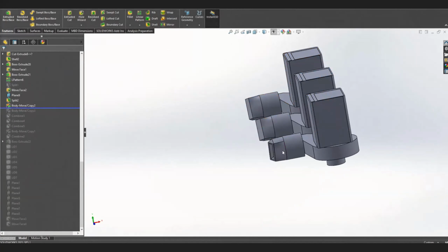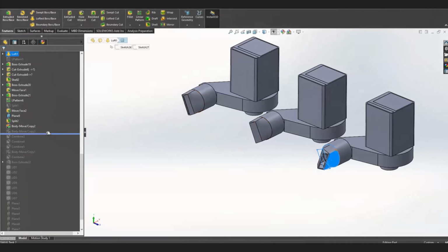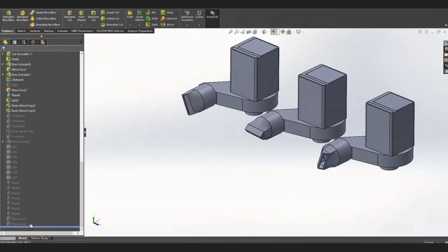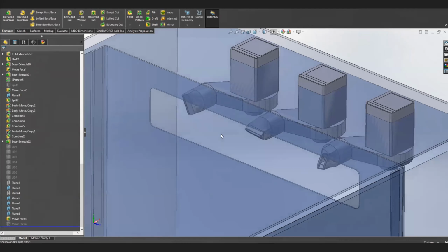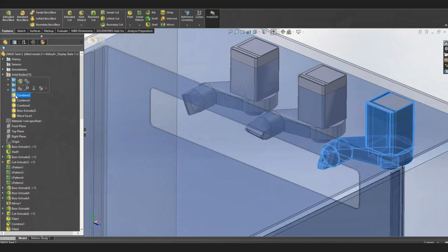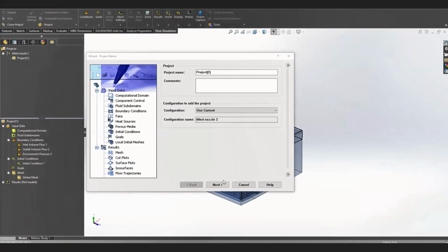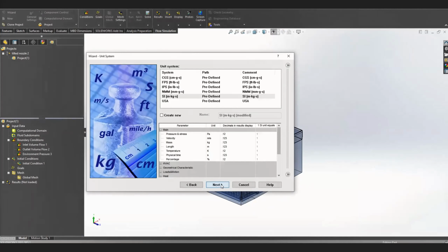So I've just split the nozzle head so that I can manipulate it easily. I've moved the body and rotated it. The pump isn't actually designed this way; we'll have to do a design change to get a new nozzle head to accomplish this. But for my analysis purposes, I'm just trying to come up with a quick way to simulate a different head position, combine it back together, and run another analysis. Then we can go to a design change to limit our time and focus it where it matters.